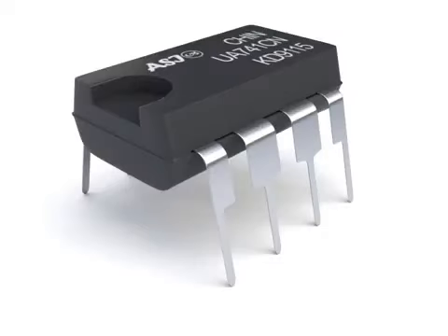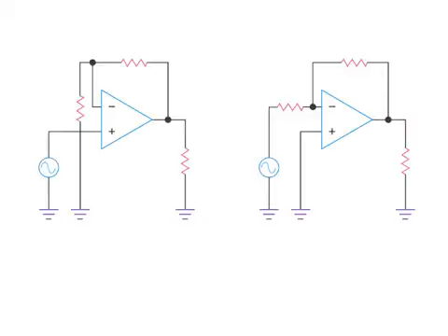Operational amplifier circuits are complex amplifiers compacted into integrated circuits, which makes them very powerful. The two most important operational amplifier circuits are classified as either non-inverting or inverting. For both of these amplifier circuits, a feedback network of only two resistors, R1 and RF, a feedback resistor, are needed to control the gain.